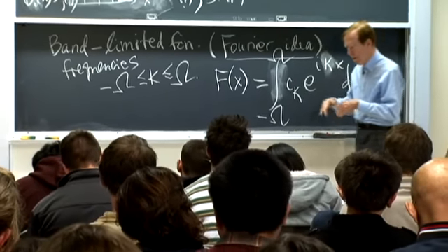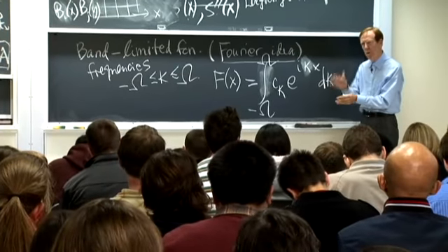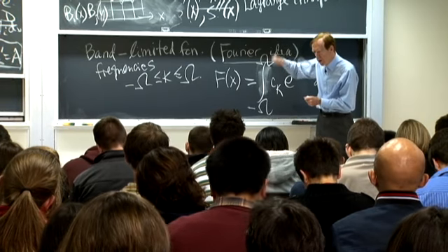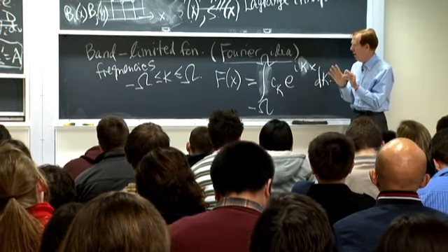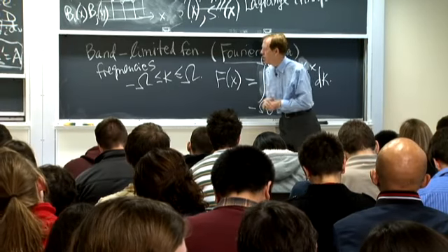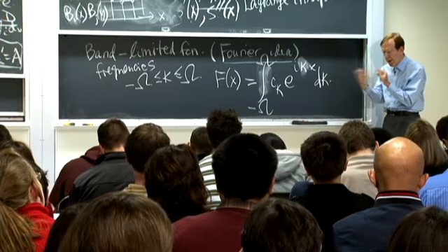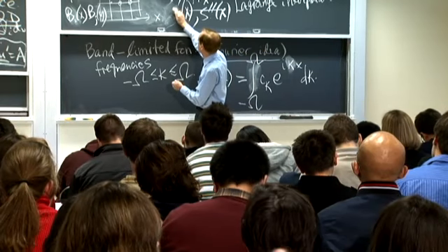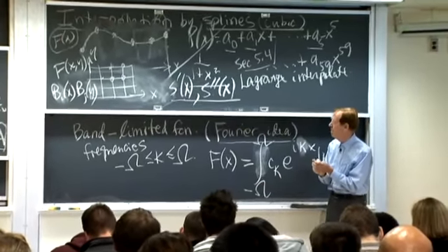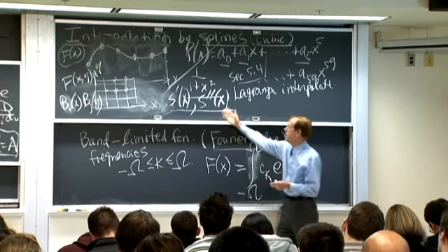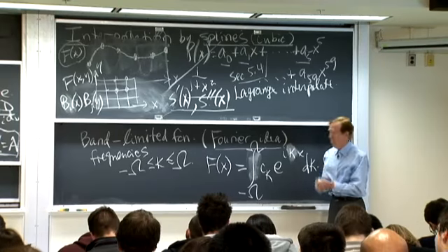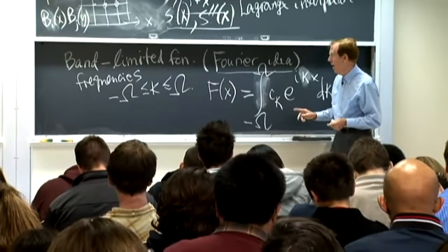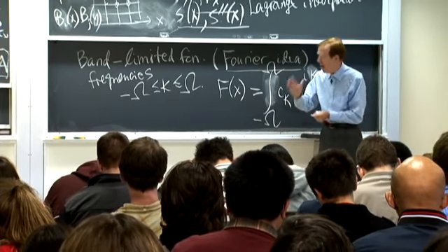That's another way to think about it: functions that have only low frequencies are associated with smoothness. High frequencies are associated with fast oscillations. So the class of band-limited functions gives me a Fourier way to talk about smoothness. For us, smoothness was something about how many derivatives were continuous. That's the sort of smoothness in the x domain. Smoothness in the frequency domain is how fast do the frequencies drop off? And here, band-limited means they drop like a shot.